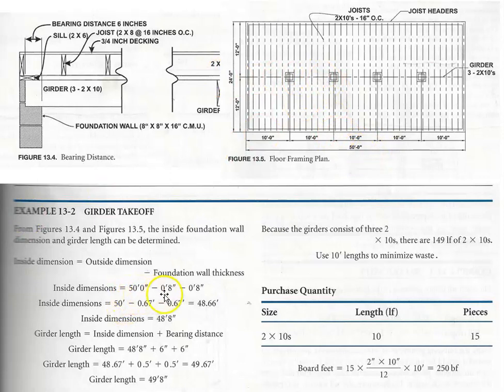So that's why right here he's subtracting the 8 inches from each side. I'm not sure why it's a full 8 he's subtracting, but if that's an 8-inch block, he's subtracted some portion of it. The overall result here is kind of negligible. It's not really so important. I don't think this calculation really changes it, but so the 50-foot girder becomes 48 2/3 feet, basically.